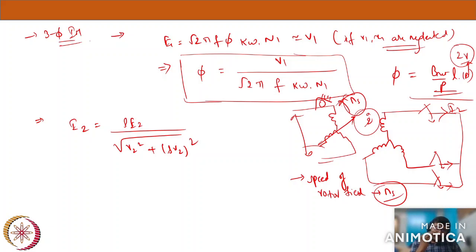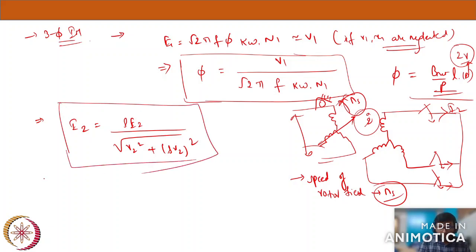Now this is an actual motor condition we have right now. The speed of rotation of the rotor field is ns, and the frequency of the electrical quantities on the rotor side is sf, and this is the magnitude of current of our actual motor condition. Now I want you all to imagine an induction motor. This is some fictitious motor we want to discuss now. So this is the actual motor condition we have stuck at this point. Now we have come across a problem: how to join these two circuits when slip comes into the picture. So this is our actual motor.